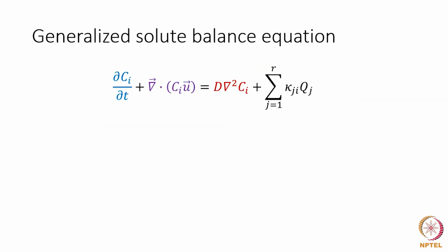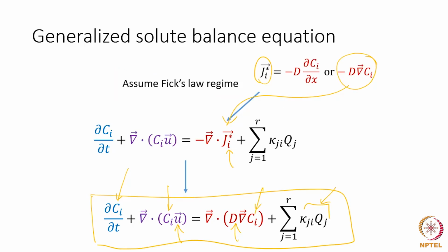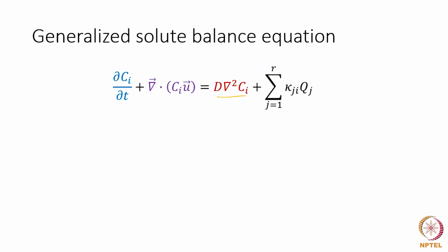Here is the equation, and we have modified the diffusion term on the right-hand side with the Laplacian, because we notice that the diffusivity, if it is taken as a constant across the locations, can be taken out of the nabla symbol, and therefore we can write it like this. So we basically have taken the D out, and we have nabla dot nabla, which gives you the Laplacian here. So this is the equation we are familiar with: the transient term, the advection term, the diffusion term, and the source term. The four-part governing equation is now ready for us.